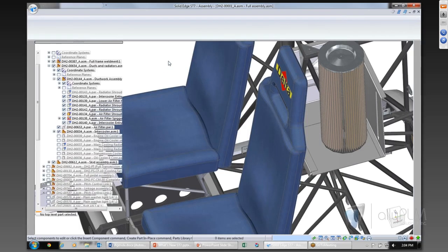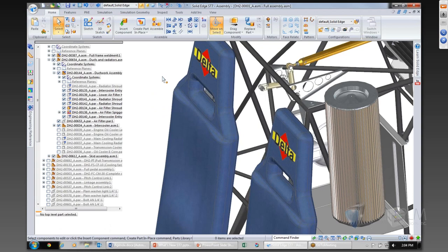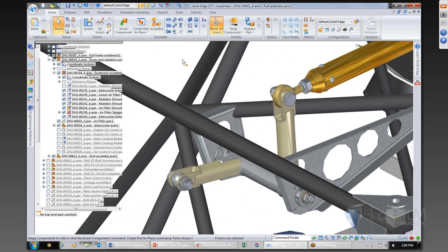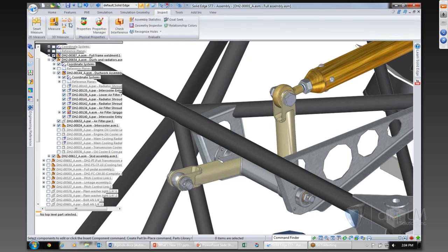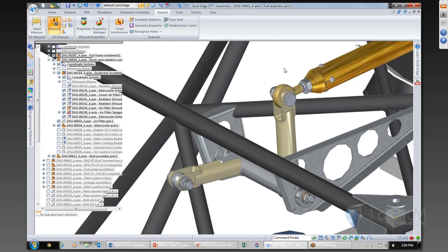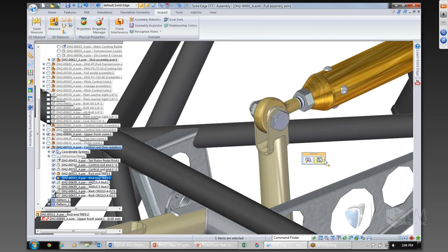Another type of part that would have taken multiple steps to create in ST6 is a spherical part. So we're going to take a look at how we can do it here in 7. Real quick, I'm going to inspect this just to get a dimension of this sphere. 16 millimeters. I can turn off my dialog box and close out of this because I can just remember that measurement. And I'm going to edit into this part here.